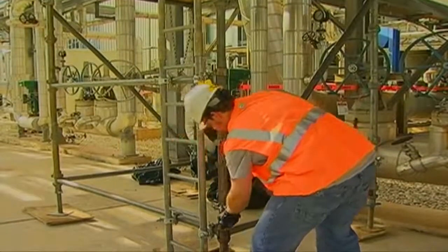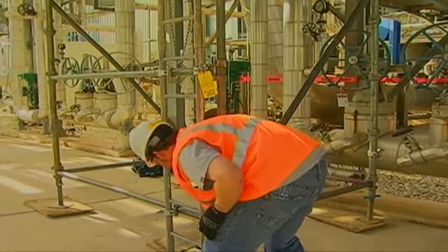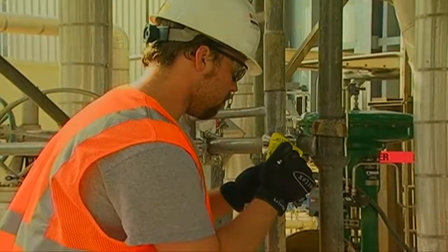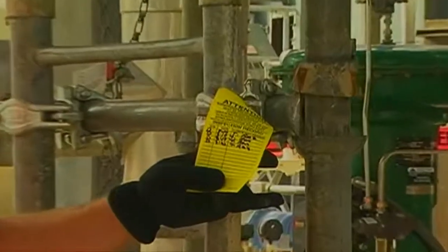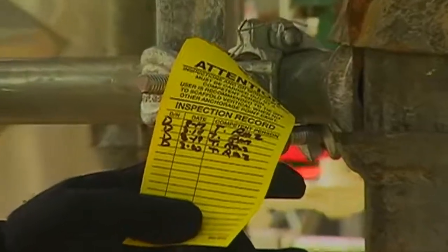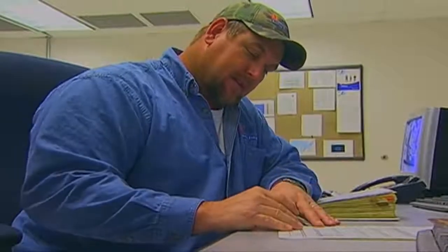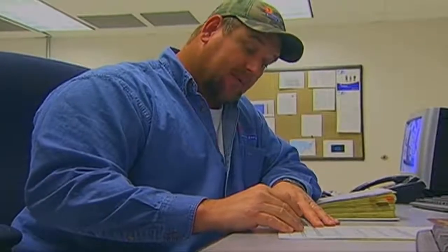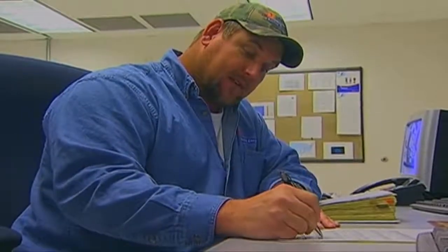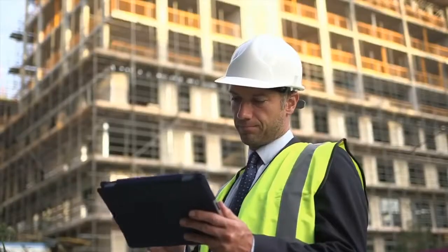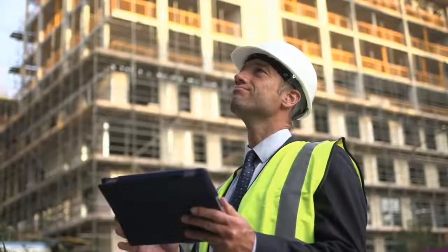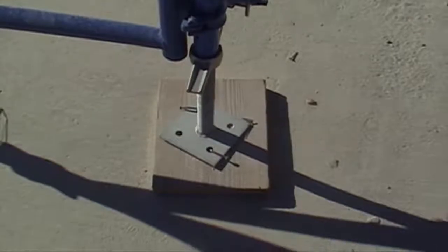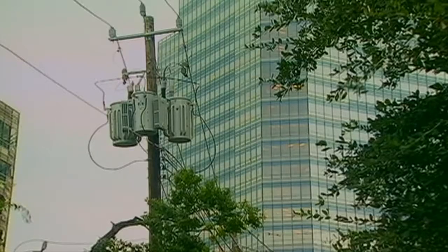One of their most important functions is inspecting the scaffolds. Scaffolds must be inspected, including scaffold components, for visible defects before each work shift and after any occurrence which could affect the scaffold. A qualified person must determine the type of scaffold needed for the job and be able to design and load scaffolds in accordance with that design. As part of the design procedure, the qualified person will determine the maximum load of the scaffold, assure a good foundation, and avoid any electrical hazards.